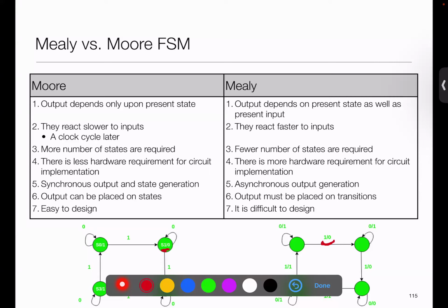I could also write a Moore machine in the same way. Instead of writing it this way, I could write it as 1/1, 0/1. I could write it like that too. You'll just have to make sure, in that case, that all outgoing edges of a state have the same output.